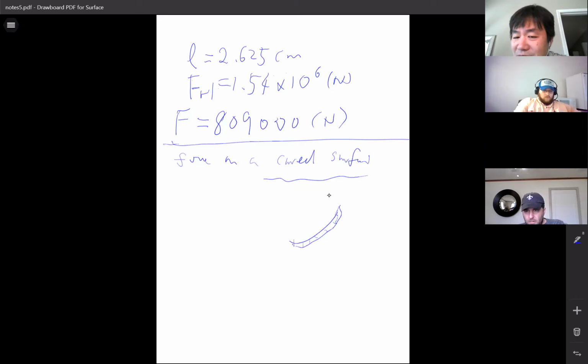It turned out in the plane surface, we actually derived it. A lot of terms canceled out, and it turned out to be a relatively easy form. You don't really need the integration for plane surface. But for curved surface, if you go directly and use the integration, you cannot cancel anything. You're going to keep the integration sign there. So in other words, you probably need to do integration to directly calculate the total overall distributed force on the surface. That's the standard procedure.